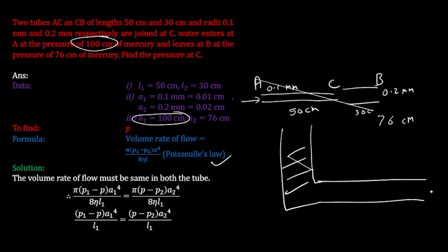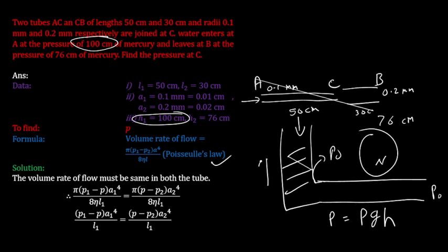At the open end of the tube, there is a pressure of atmosphere, and at the opposite end of the horizontal tube, there is already the pressure of atmosphere from this open mouth of the vertical tube, plus the pressure due to the weight of the liquid in the vertical tube. So pressure difference is actually equal to the pressure due to the weight of this vertical column of the liquid, and the pressure due to the vertical column of the liquid is given by the density of liquid, acceleration due to gravity, and height of the liquid.